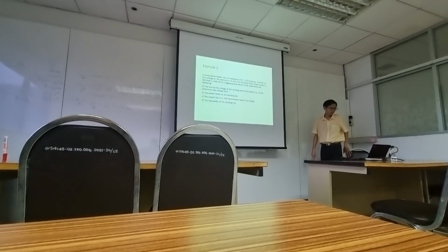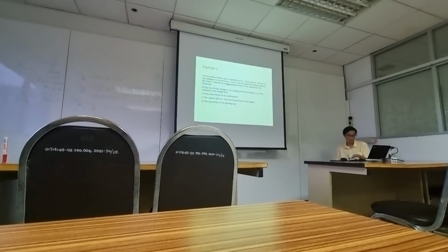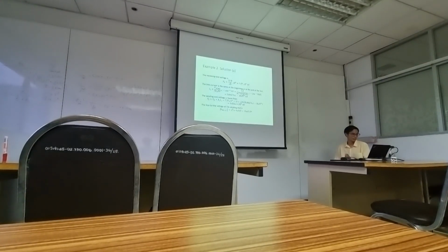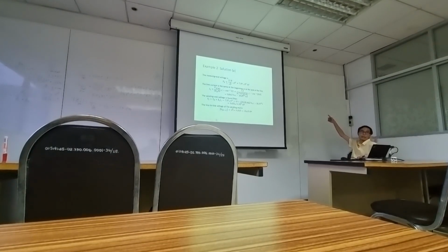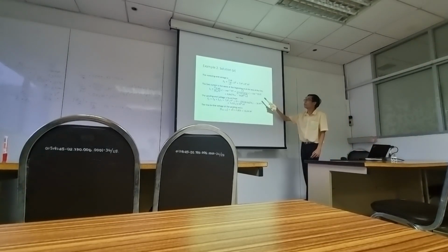First, the receiving end voltage is 13.8 divided by √3 angle 0 degrees. You will have 7.97 angle 0. So this is this voltage VR.